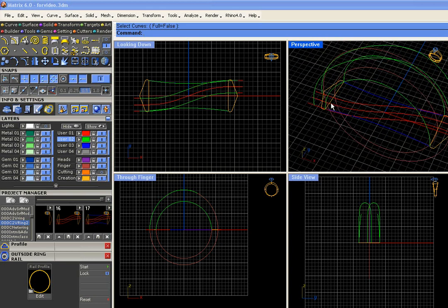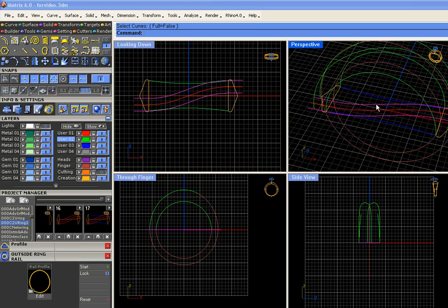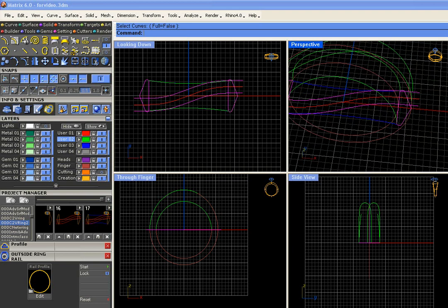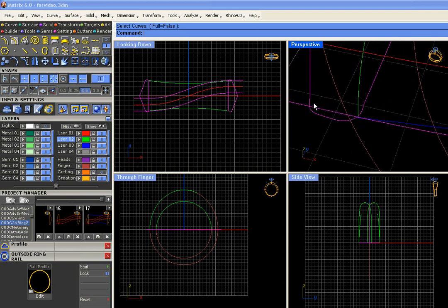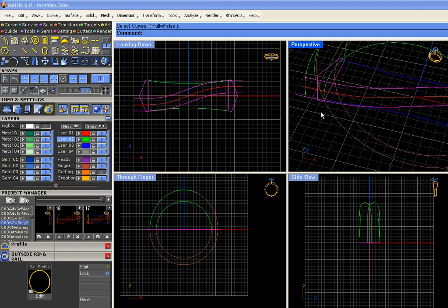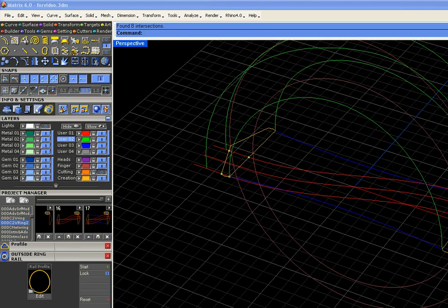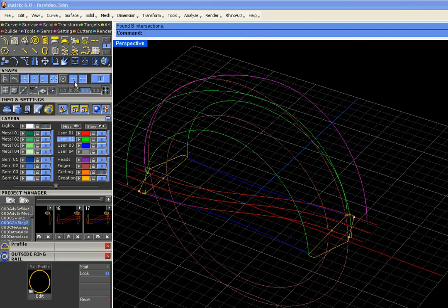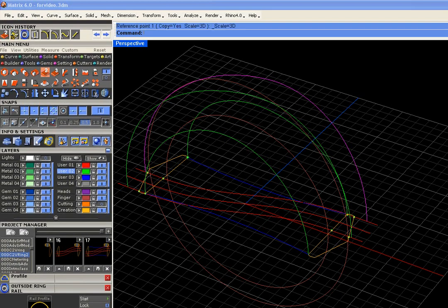So to begin, let's take the two curves, the red curves, and the two profiles, and run the intersect command. This is going to give us point objects right where they cross, giving us a place for us to snap the curves to, so we have an exact location. So go ahead and run intersect. Okay. And the green curves on the top here are the ones we're going to try and fix. We're going to do that with the orient 2 points command found in the transform menu.